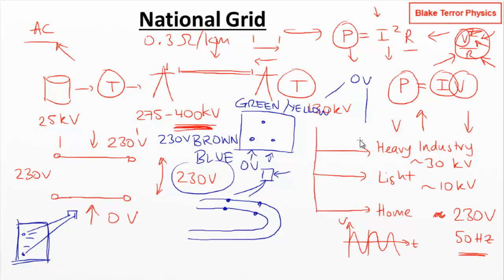You've got a quick route down to earth, that's how earth is represented on the circuit diagrams. You have a metal spike underneath the house, just stuck in the earth, and it's giving us a quick escape route for current if something goes wrong. And then you'll have the fuse sitting inside the plug as well. The fuse is really there to protect the cable that goes off to the appliance, rather than actually protecting the appliance itself. You don't want the cable melting or getting too hot or setting alight.